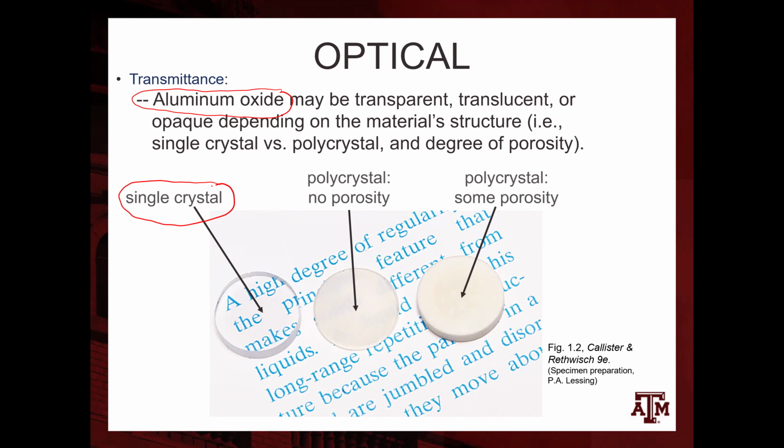except the microstructure. So it is this underlying microstructure that we cannot see by the naked eye, but we can see under the microscope, and we can use different manufacturing methods to induce those different microstructures. We can use that to change the properties of a material even without changing the material itself or its composition. And again, that speaks to this important relationship between the underlying structure or microstructure and the properties of the material.